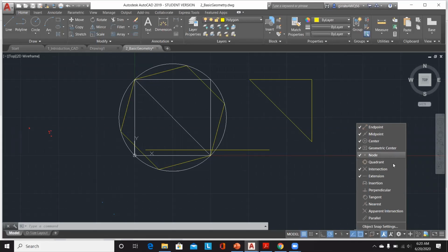Similarly, if you want to snap to the intersection of lines or extension lines, you can click those options that will help you choose the particular line segment. Similarly, if you are drawing complicated geometry, and you wish to select the exact point of intersection of a tangent and the line, you don't have to calculate or recreate those drawings. You can use a simple feature by clicking the snap that will let you select the point that is intersecting with the tangent.